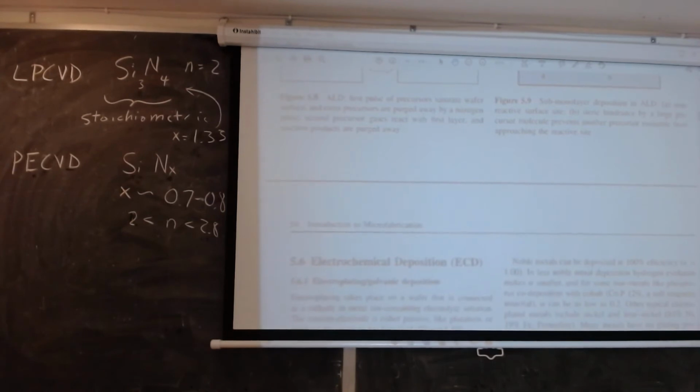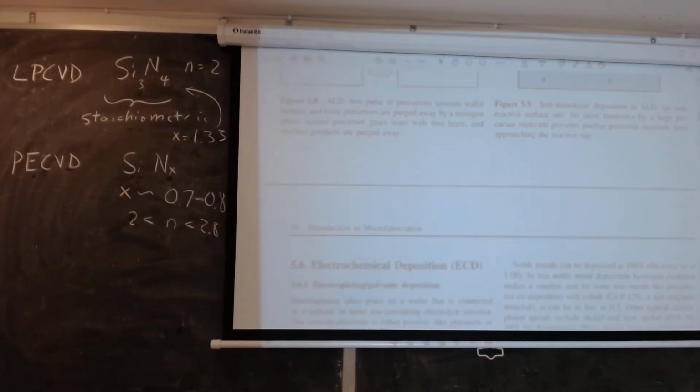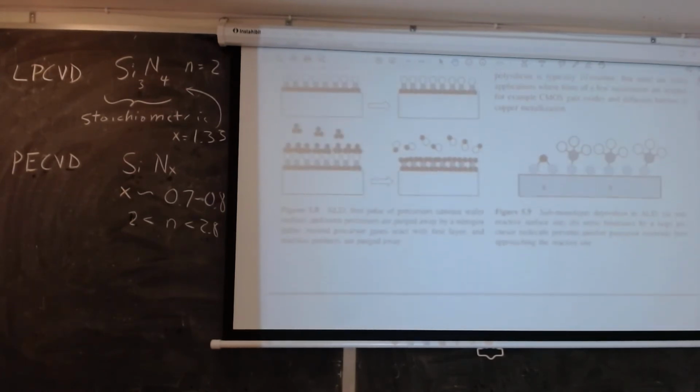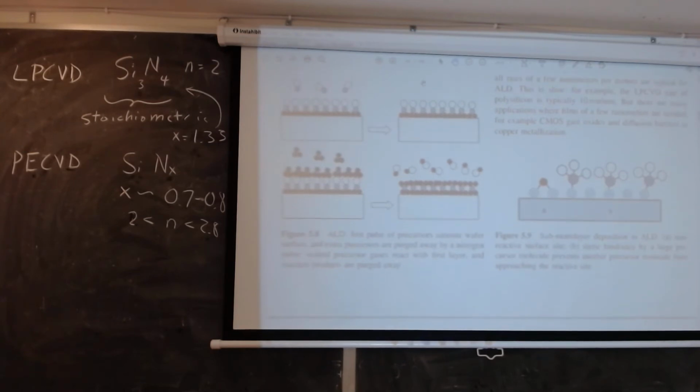Sorry, okay, so that whole discussion, hopefully, of atomic layer deposition, let me go back to this figure. The point is it's a cycle of one type of monolayer or atomic layer, followed by a second type, followed by the first type again. And so you run the reactor in this sort of two-cycle period and deposit one atomic layer at a time that way.